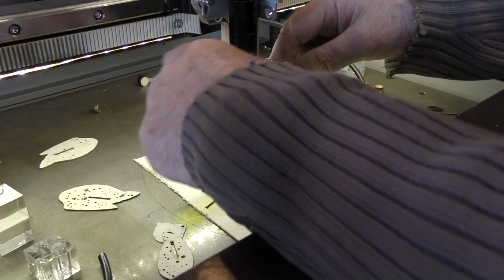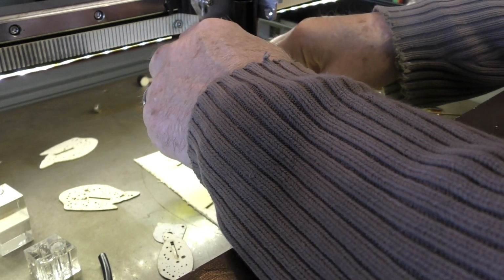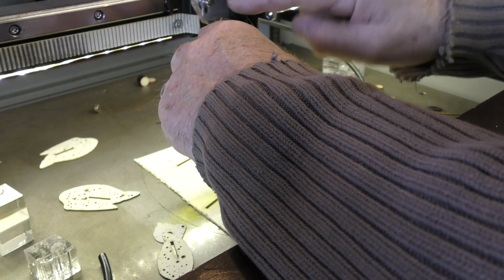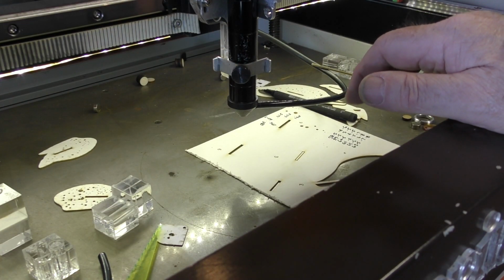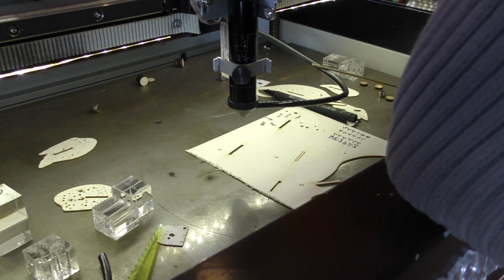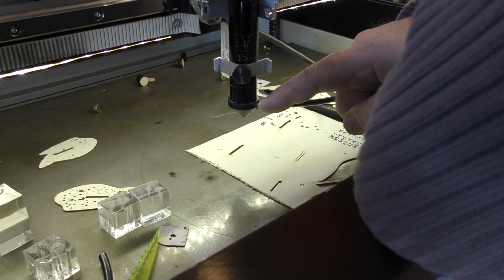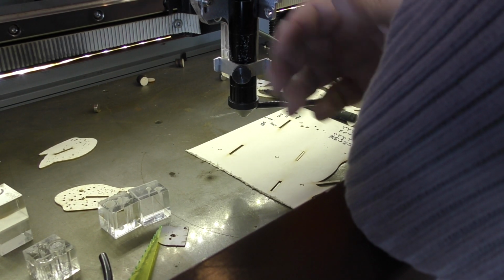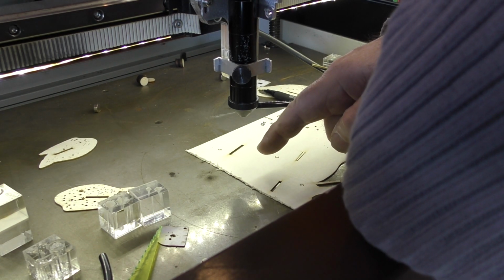The best focal point we found on the other machine was 59.5. So we're going to start this off using exactly the same pile of blocks and beam and set it up exactly the same, 59.5. I've got the same 50 millisecond pulse set on this machine. So, direct comparison. This one is set to 100% at 30 watts. The other one was set at 70 watts. This is using half the watts in the same time.